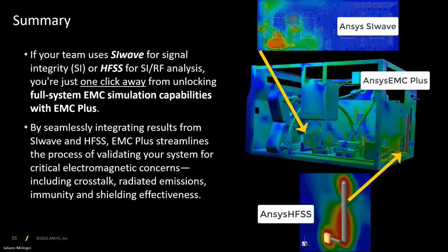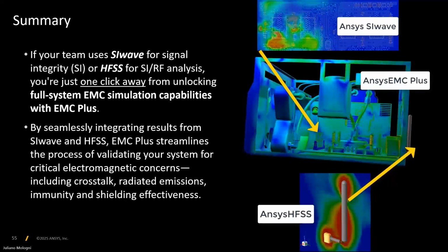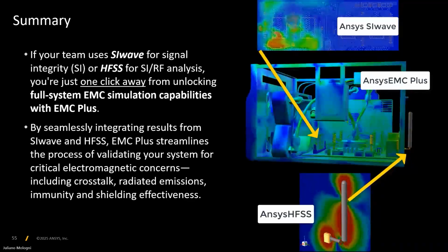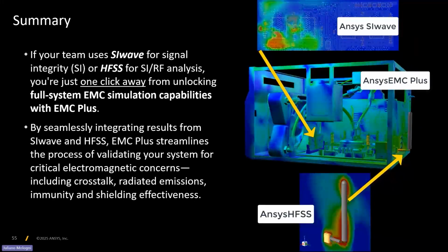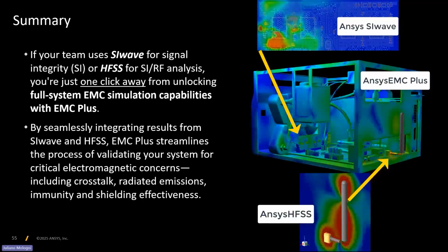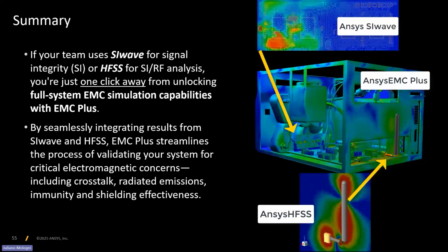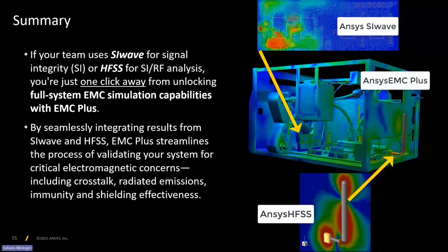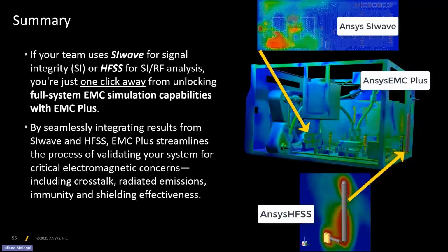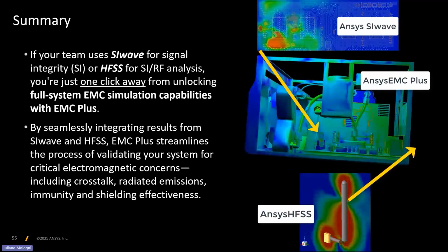Excellent. Next question is, the mesh in EMA's products, I assume this attendee means EMC Plus, FDTD type of structured mesh, does it have localized refinement? Correct. So there, finite difference time domain, it is a grid. You can have a subdomain with smaller mesh cells, but it's not like adaptive mesh refinement like FEM in HFSS.